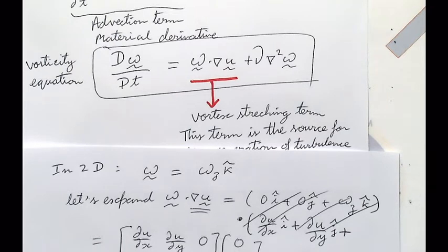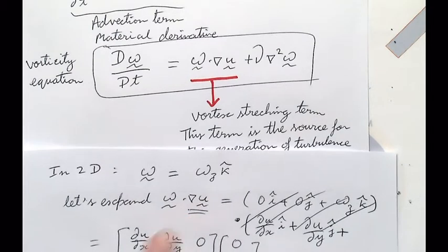So this vortex stretching term is what gives rise to that cascade of energy. Okay? So energy is being transferred from bigger scales; the vortex stretching term destroys this bigger vortex and keeps creating smaller ones out of it.